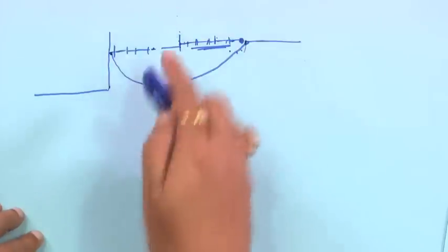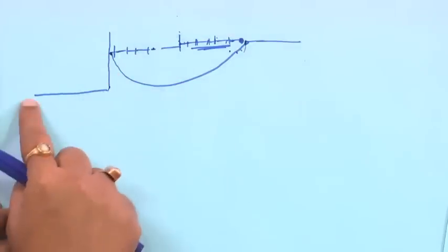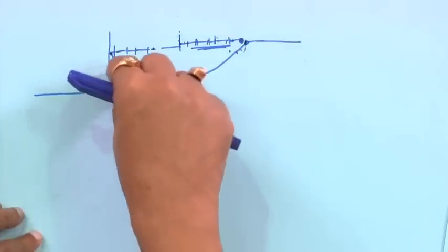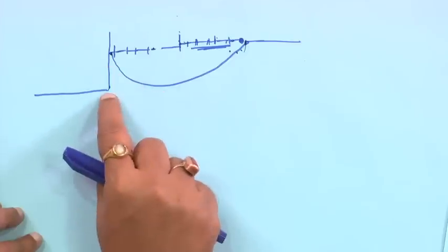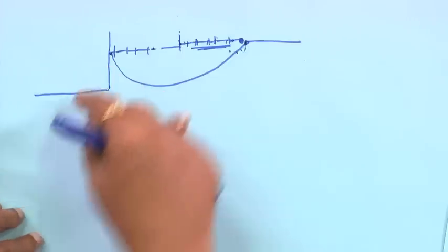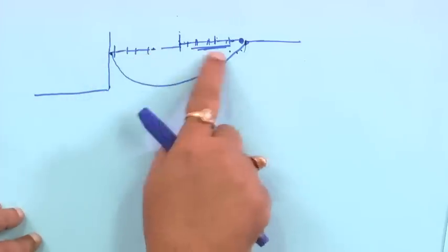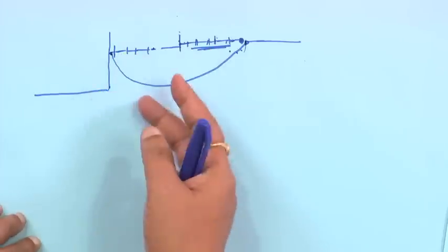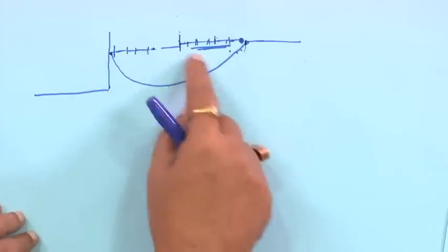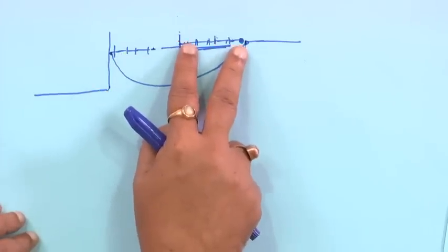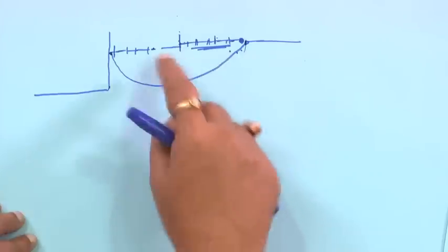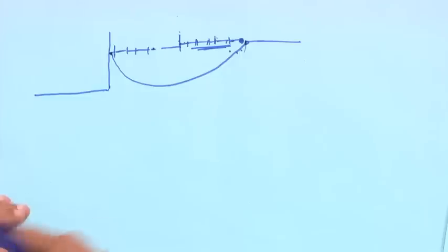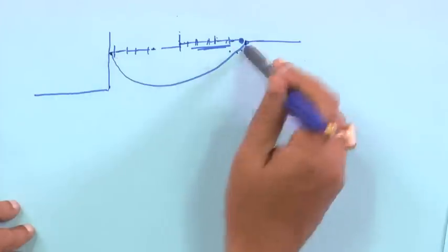Sometimes the conductor is coming like this and going like this. Somewhere it will be tension type, making it horizontal so that the conductor is in tension, and from there you can find another one, maybe in the same horizontal position, or depending on the design, maybe a vertical position, but it will be connected by the same conductor.